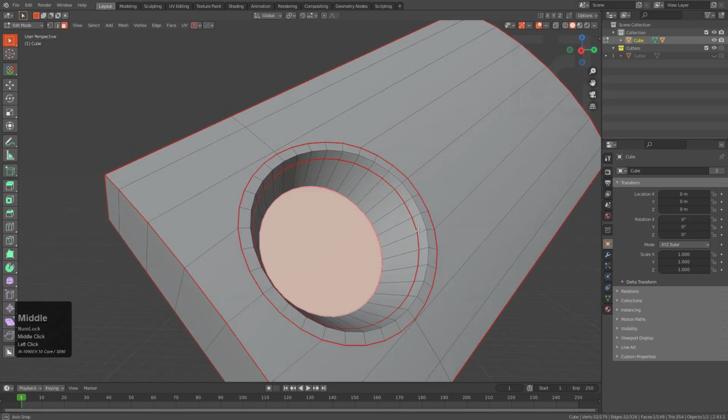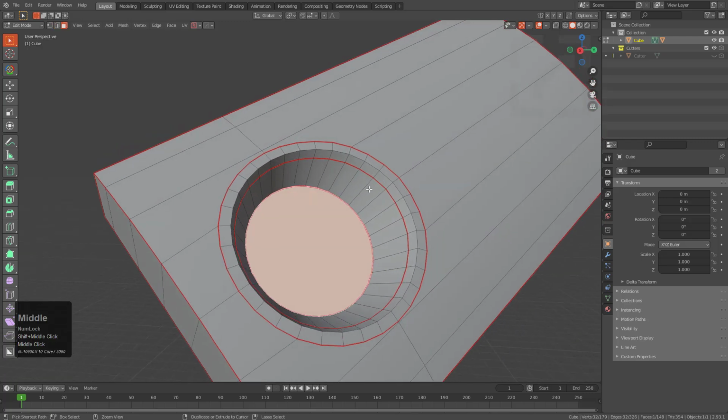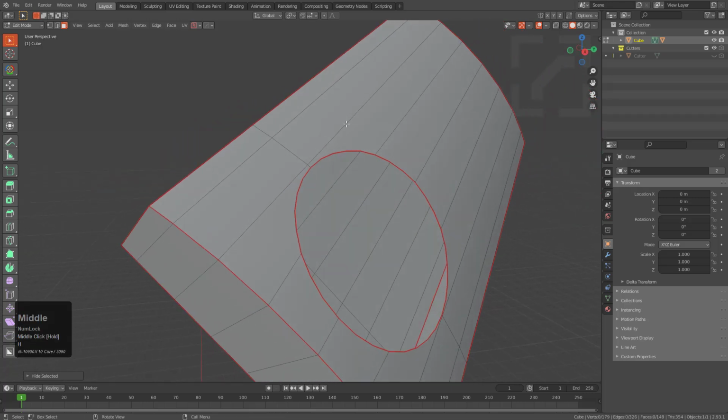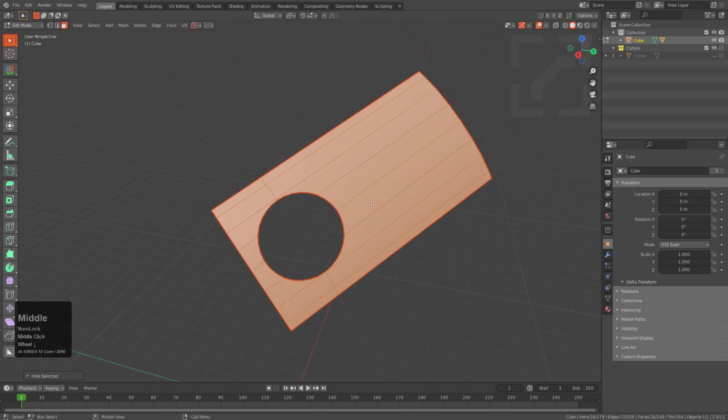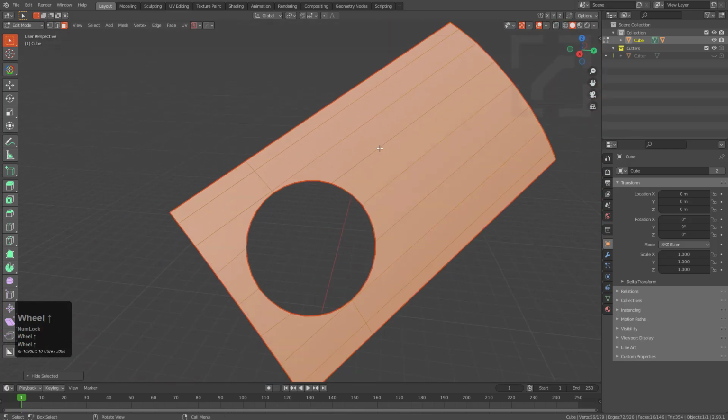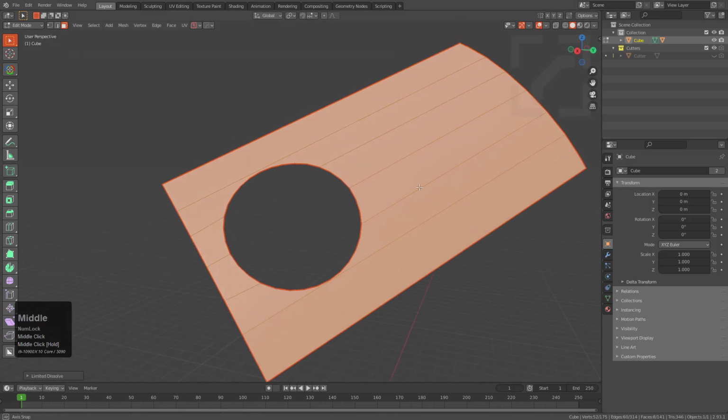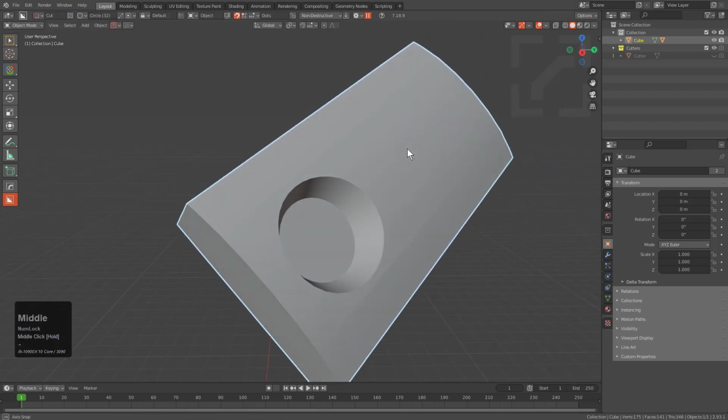And over the last few examples, I got a little bit more experimental with the surface, but this time I actually want to hold the surface in place like you're seeing me doing now, where I didn't replace the original topology just yet. But now I'm going to press X and just do a limited dissolve to just get rid of what can possibly not have to be here anymore.